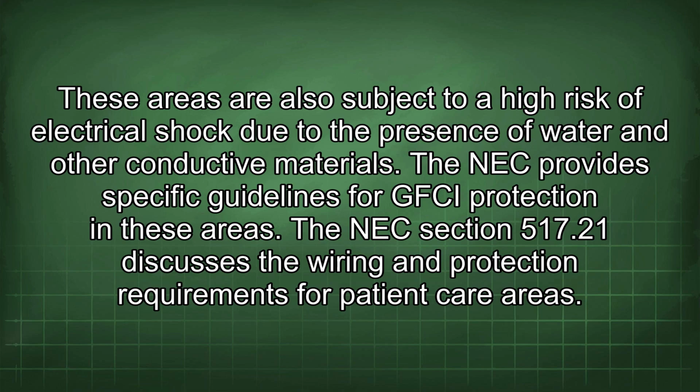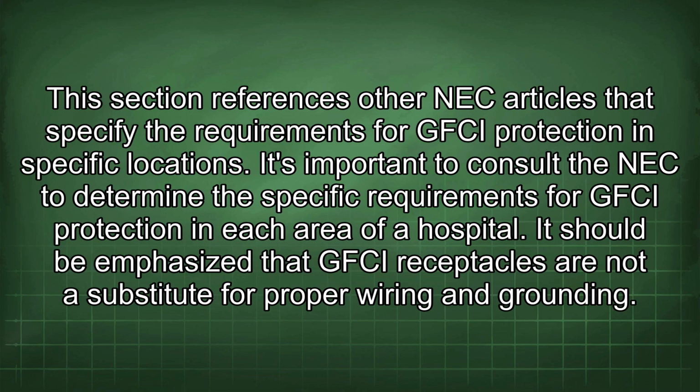The NEC Section 517.21 discusses the wiring and protection requirements for patient care areas. This section references other NEC articles that specify the requirements for GFCI protection in specific locations. It's important to consult the NEC to determine the specific requirements for GFCI protection in each area of a hospital.